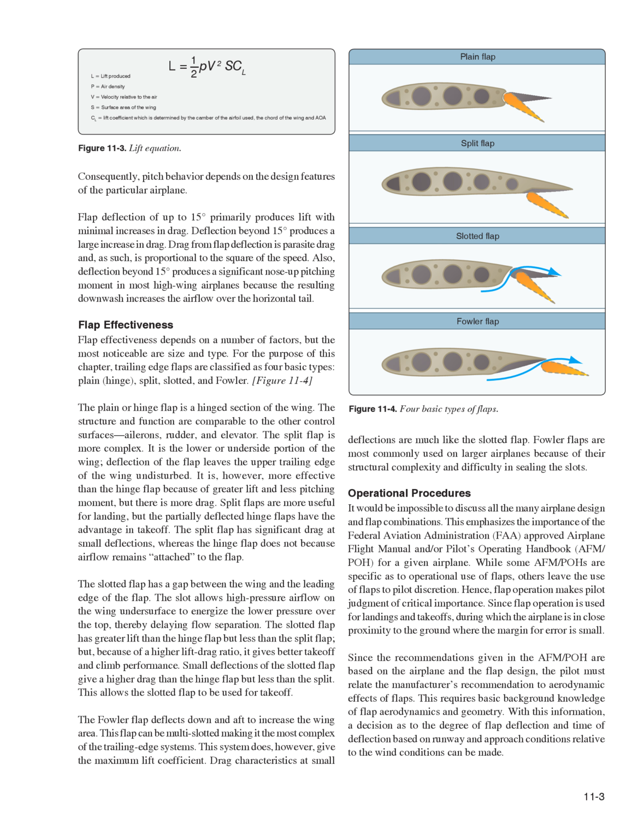Since flap operation is used for landings and takeoffs, during which the airplane is in close proximity to the ground where the margin for error is small, and since the recommendations given in the AFM/POH are based on the airplane and the flap design, the pilot must relate the manufacturer's recommendation to aerodynamic effects of flaps. This requires basic background knowledge of flap aerodynamics and geometry. With this information, a decision as to the degree of flap deflection and time of deflection based on runway and approach conditions relative to the wind conditions can be made.